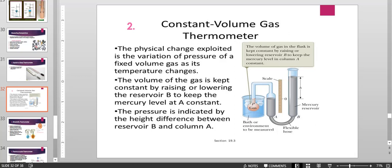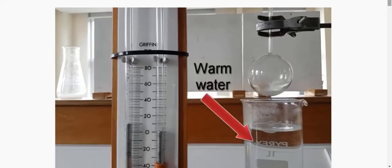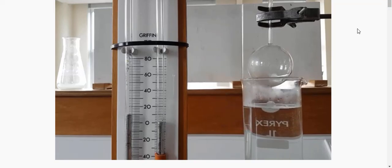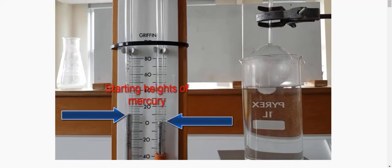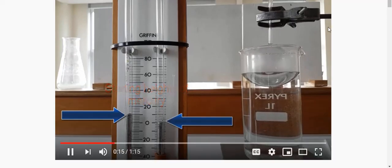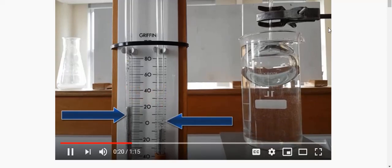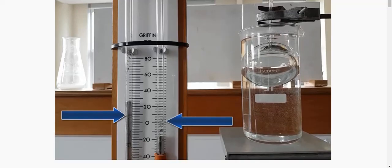So dear students, let's now have a view of the practical performance of this thermometer. So now we're going to see the gas thermometer working. So we're going to raise warm water into the gas, and the gas will expand. Notice we've got the starting levels of the mercury with the two arrows there. Then as the warm water heats, the gas will expand, which will force the mercury down on the right hand side and up on the left hand side. But this will also increase the pressure as well as the increase in volume.